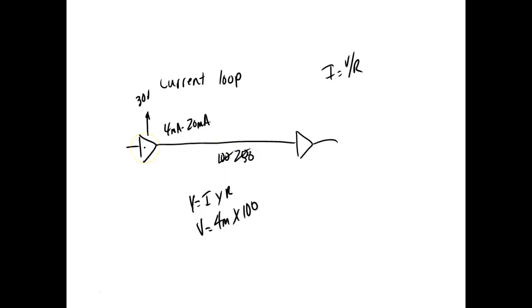Well, this is what we call a constant current source. What it's going to do is automatically raise its voltage to keep the same current flowing, as long as I don't exceed the range of the current amplifier. If the current amplifier has to get up above, what, 30 volts, it can't do that anymore, right? You understand?